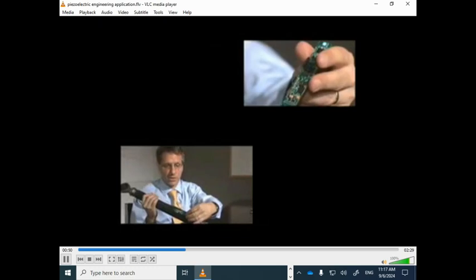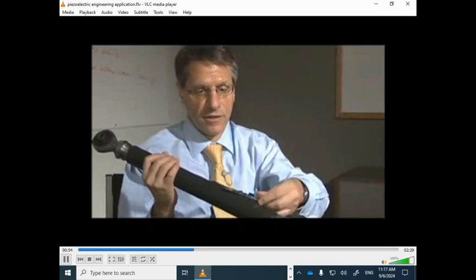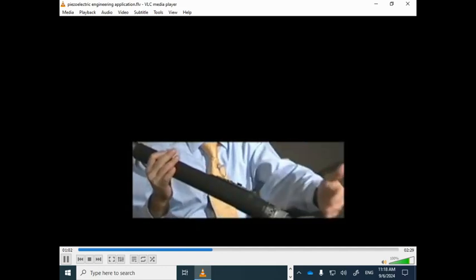Well, there's a board, we call it the pitch link board. It lives underneath all this protective covering. And attached to the pitch link down here are strain gauges, and those strain gauges are set up to measure the tension and compressive loads that this thing sees.